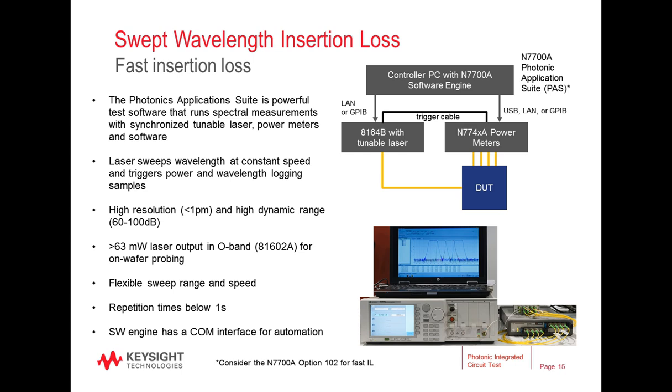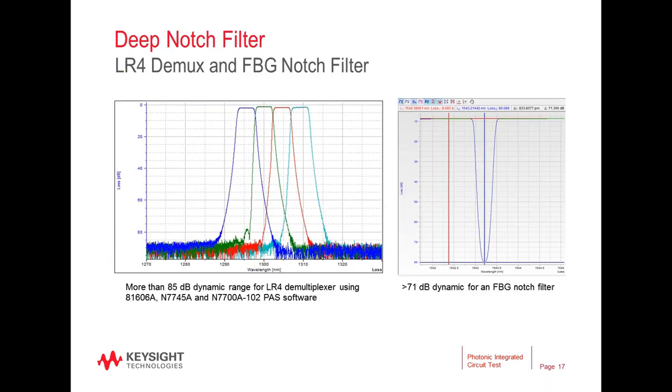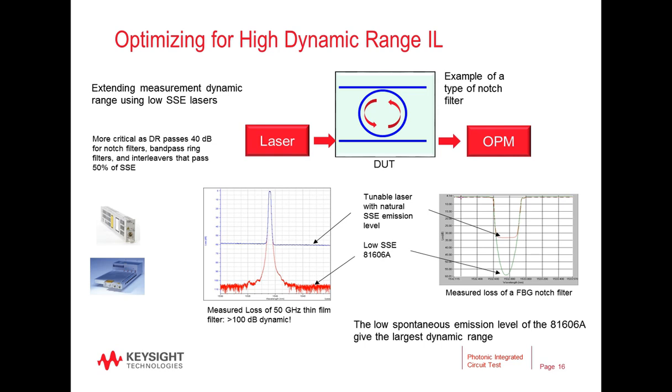I'd like to note that a good practice with optical test systems is to reduce the number of optical cable connections and keep fiber length as short as possible. This is particularly important with polarization maintaining fiber due to cross-coupling effects you can get at each connection, and that can cause measurement instability due to interferometric effects. Cleanup polarization splitters may be used, but attention must be paid to power calibration and drift following the beam splitter.